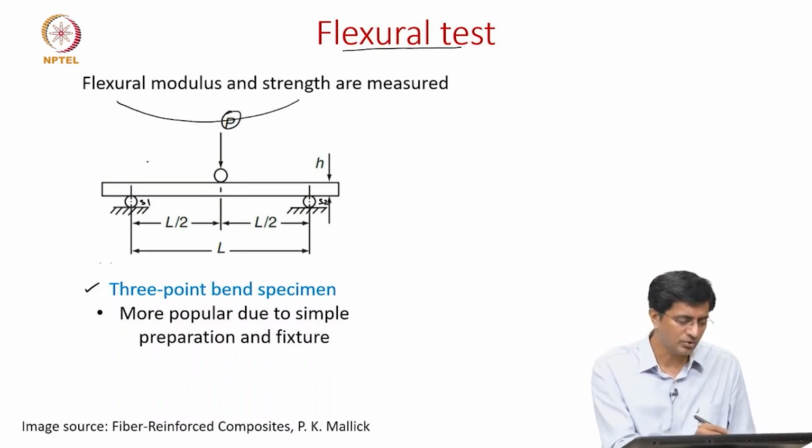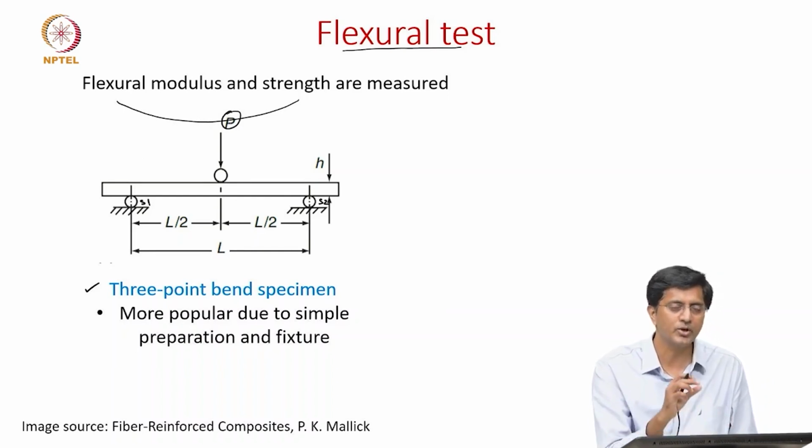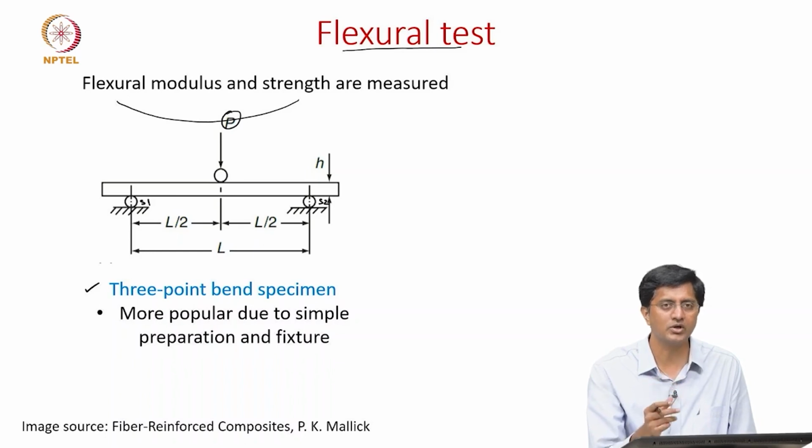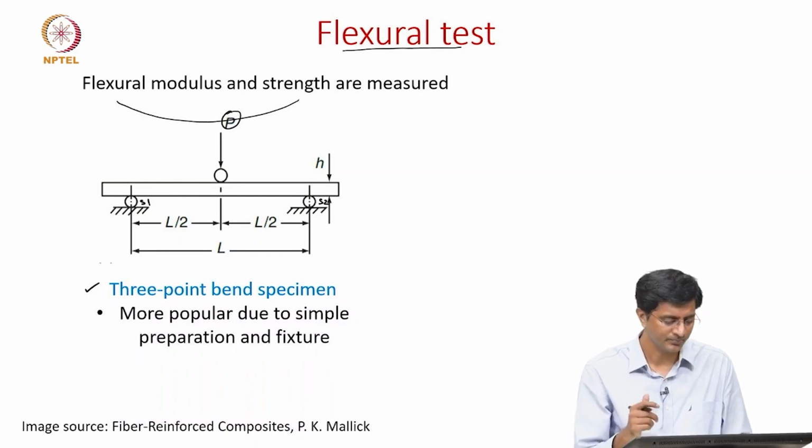And once you know the load, and once you already know what the deflection of this laminate is, one should be able to find out the flexural modulus as well as the flexural strength using the basic strength of materials formulas.